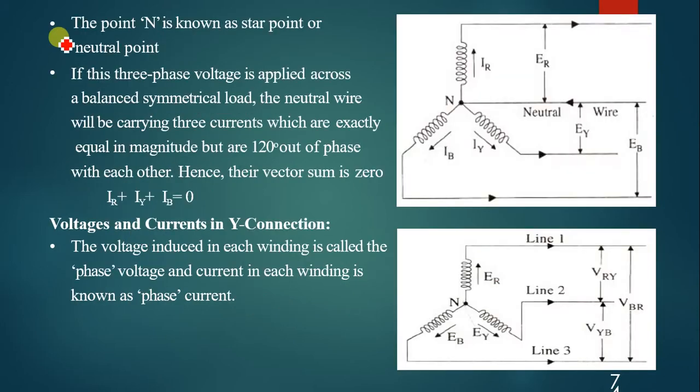First, let us check how this star connection or star configuration looks. Look at this figure. You have one end of a coil. This is one load, this is another load, this is another load. All these loads are connected together to get a common node called N. This is called the neutral node or neutral end point. Between R and neutral, what kind of voltage can you get? It's a phase voltage, which is 230 volts.